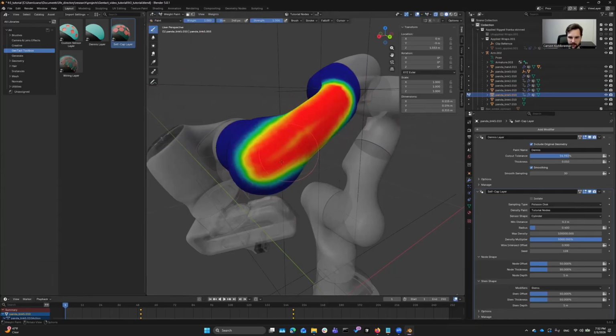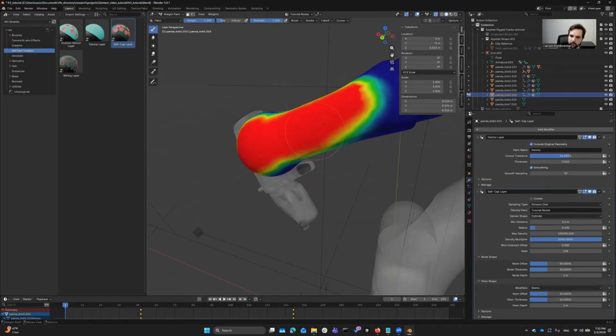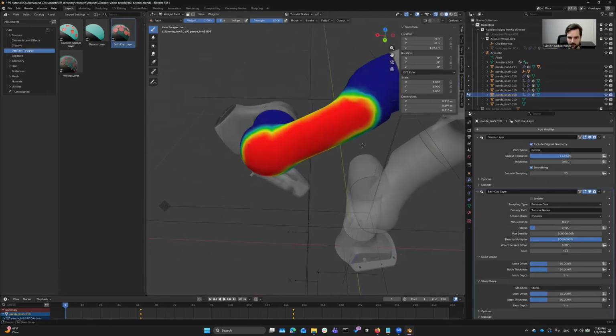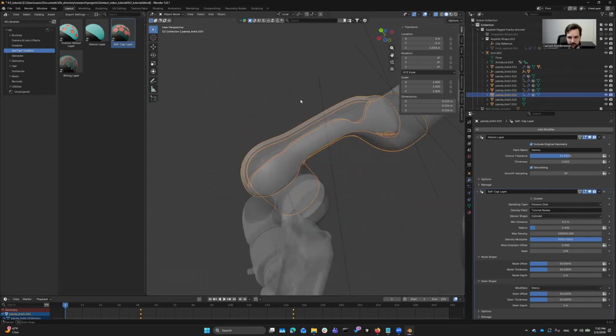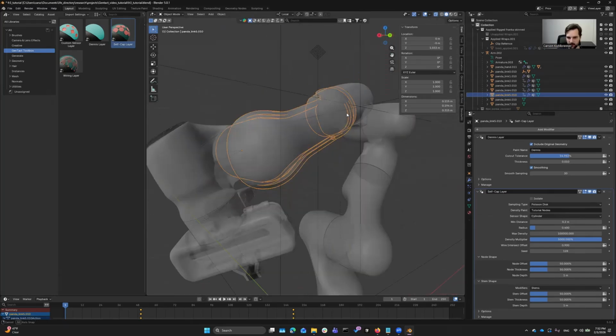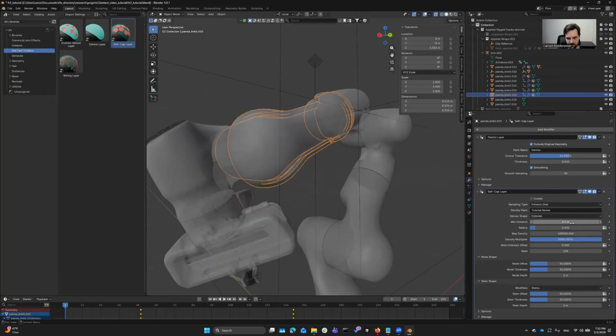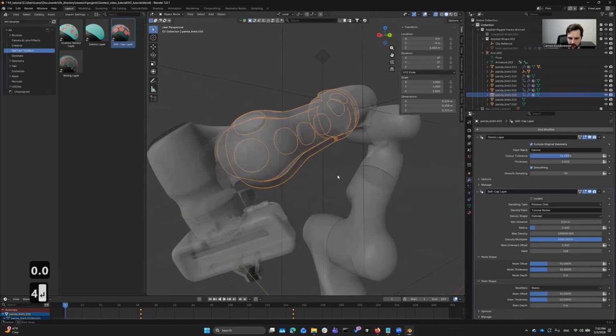And you probably will notice that you can't see anything. That's because in weight paint mode, you can't use X-ray mode for the visuals. To fix this, just go back into object mode and see what you've done. Currently, nothing's showing up because I actually have the density set too high, or too sparse. Right now, it's 0.2 meters per nodule. I want that to be a little lower, so I'll do 0.04 meters per nodule. There we go.